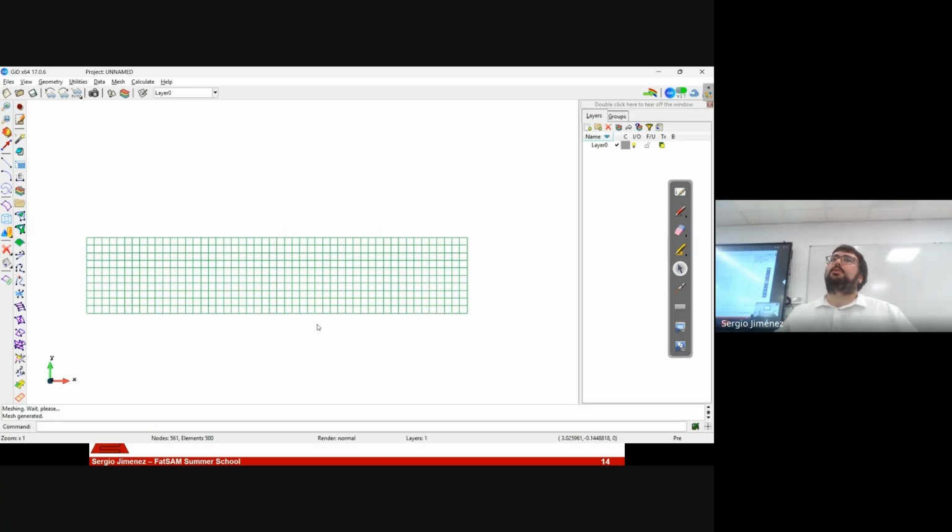Okay, so at this point, you know how to create a geometry, basic one, straight lines, points, surfaces, and so on, and how to move from this geometry towards the finite element mesh. This is only GID. I have not used Kratos. This is just GID. And then, once you have the finite element mesh, you import the calculator, which is Kratos, okay, or whatever other problem type that you want to use.